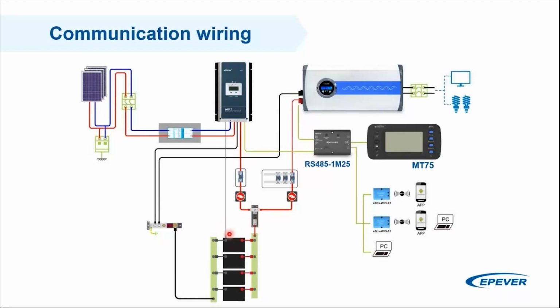As an example, we have a battery temperature sensor connected to a charge controller, for instance. And it tells us that we should stop charging the battery if the temperature rises above a certain threshold. So it's important that this value is communicated between the components of the system, or this inverter can be shut off if the battery voltage goes below a certain threshold.